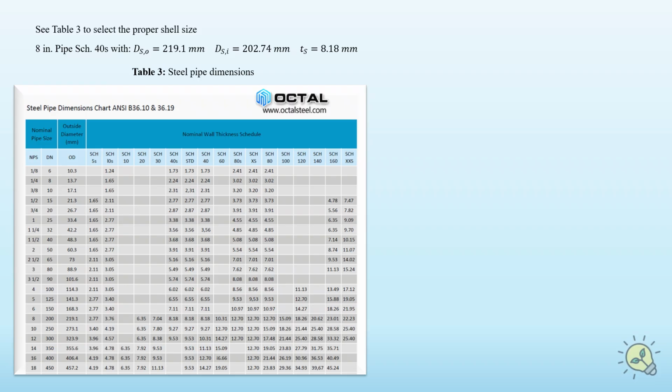Outside diameter of the shell is 219.1 millimeter, the inner diameter 202.74 millimeter, with a thickness of 8.18 millimeter. And now we have finished that part.